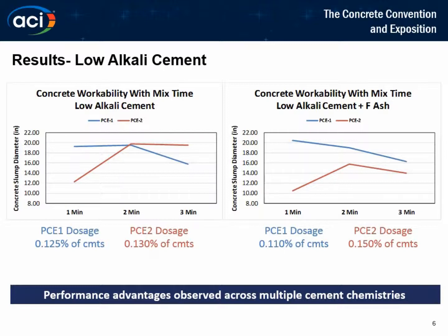No, because you achieve your ultimate workability, you know what it is. If you're targeting an 8-inch slump, your general purpose PCE gets you there, I'm making this up for example's sake. Your general PCE gets you that 8-inch slump in 2 minutes. You know that 8-inch slump is where you want to be. A faster dispersing polymer gets you there in 1 minute. You don't have to leave it in to see where that mix goes. You've already achieved it at 1 minute. Does that answer your question?